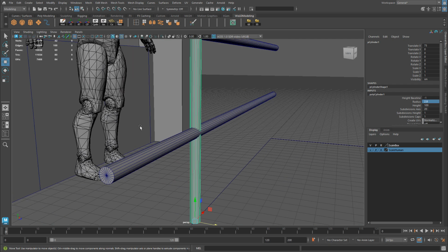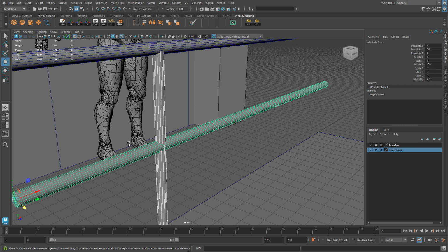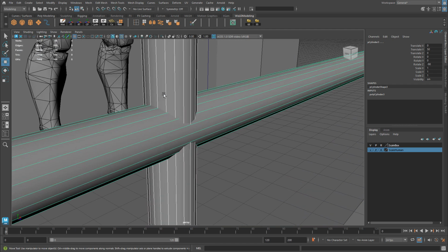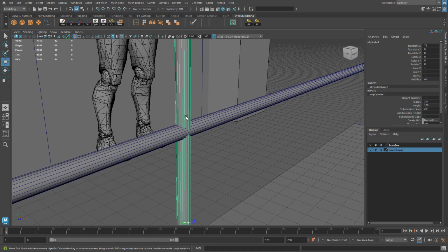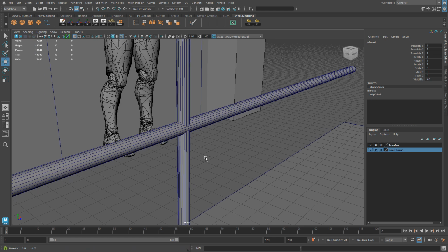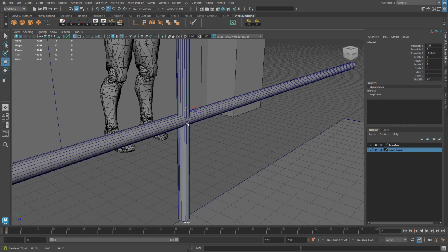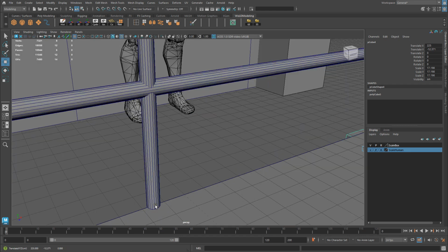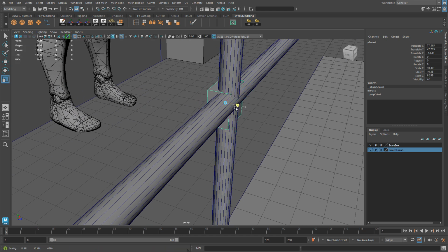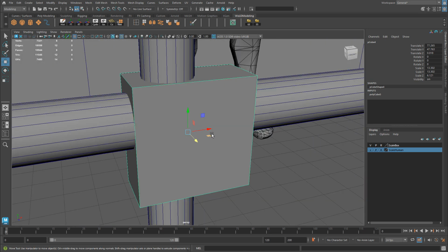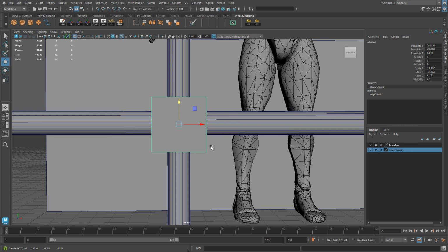Now again, your other option is to weld it together and actually model those pieces so they are welded together as one single model instead of two pieces sitting on top of each other and overlapping. That's one option. Another option is to create an additional piece. For example, this is just a quick little option you could use: you would introduce a whole new piece of geometry, let's say maybe a cube, could be a cylinder, and let me snap it right there just so I can show you, and essentially create an additional piece of geometry that would hide whatever overlap you have, like so, kind of like a welded piece that keeps these two railings together.